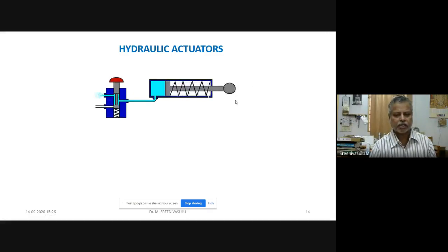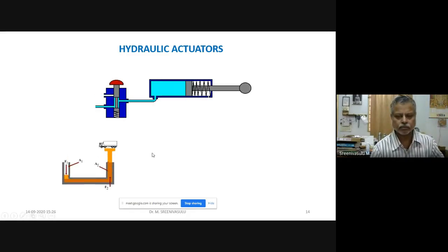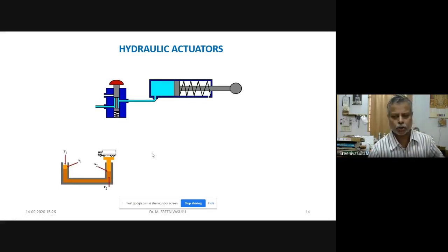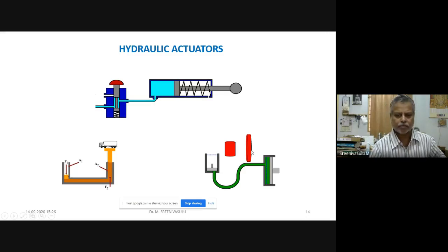Now this particular image is trying to give you a sort of animated image wherein for an applied small pressure we will be able to make even trucks be lifted. It is quite possible. And of course, the principle behind this has been shown here. Here actually greater volume, lesser area, but more distance this particular piston is traveling. This red color is trying to indicate the volume that got displaced. And this red color is trying to show the volume that has got displaced. Both the volumes are one and the same.